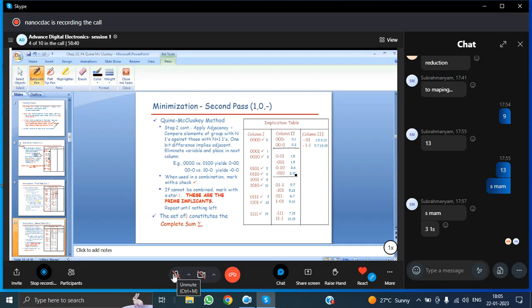Now we will just see column 2, and in column 2, look at groups 1, 2, 3, 4. And now you can see the prime implicants. These are the obtained prime implicants, extracted from column 1. So among these, look for terms that are similar with at least a 2 bit variation. So what are these? 1 5 and 9 13. This is 1 5 and this is 9 13. Both are matching, right? Look, here 0 dash 0 1.